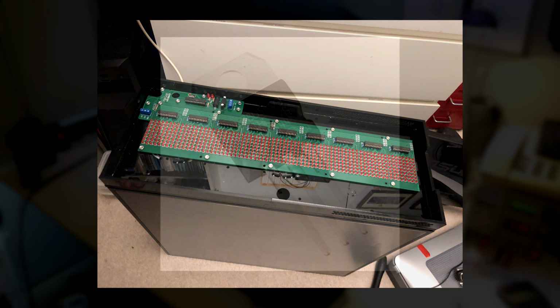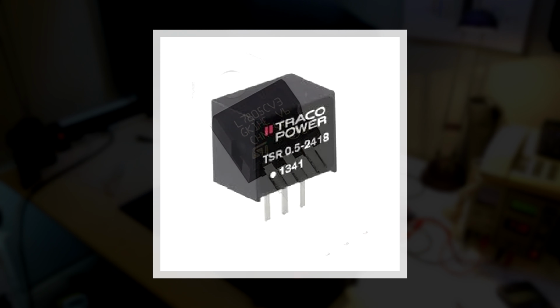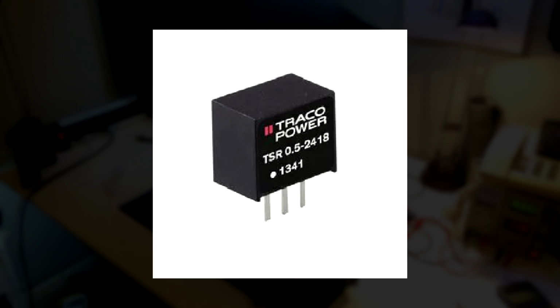I had initially planned to use an LM7805 as the 5V power supply, but it got unacceptably hot, even with the heatsink. I moved to a Traco Power 7805 drop-in replacement, switch mode, and that works quite well.